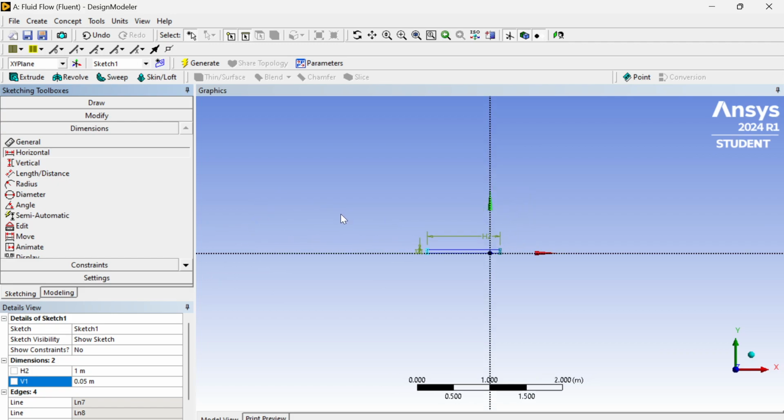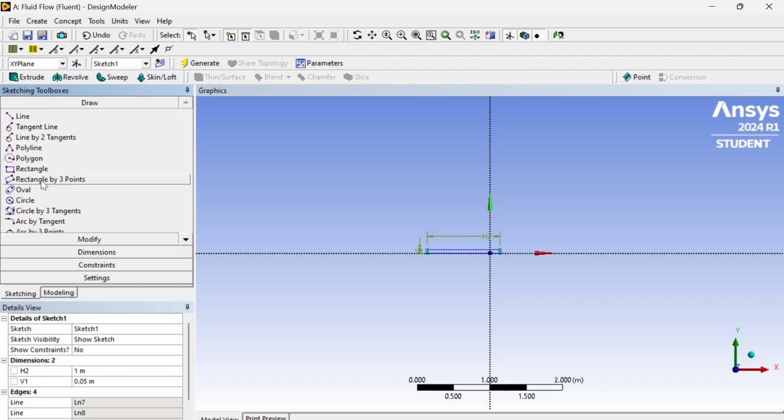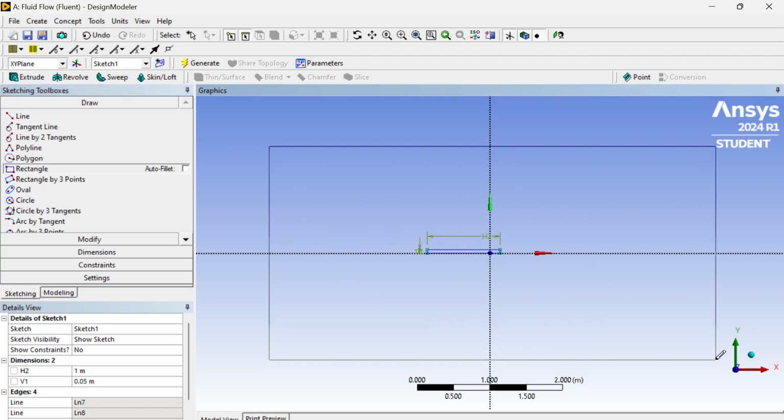And then the next thing you want to do is to design a control volume that is going to be the fluid. This control volume is going to be where the fluid is going to move in. So control volume. You just have to be as big as necessary. This big is big enough for our case. Again, this control volume is where everything happens, right? This is the fluid flow. It's going to come in from this side, and then it's going to pass through. It's going to meet this object, pass through this object. There will be a pressure and velocity distribution around this object, and then it will go out from these sides.